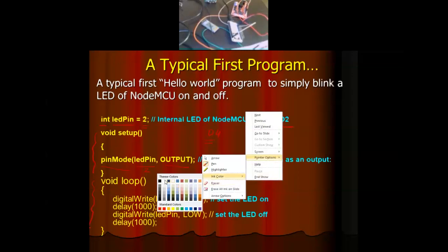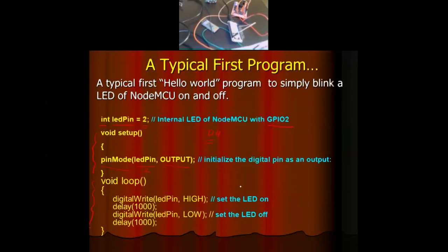But suppose instead of an output device, we are connecting an input device to some other pin, let's say pin number 3, like a switch or a digital sensor. Then I can declare it this way: pinMode 3, INPUT, where I am connecting this digital sensor.